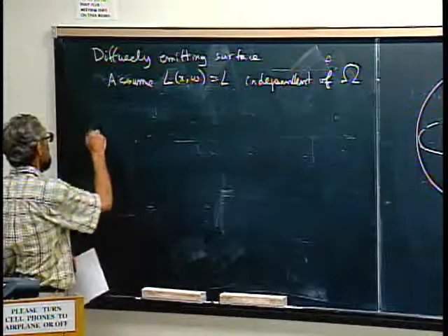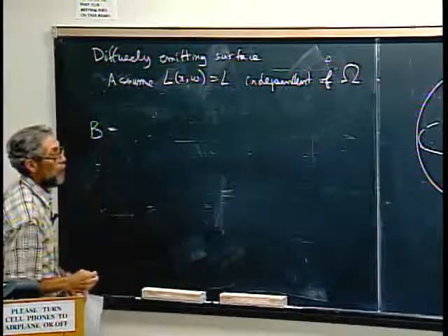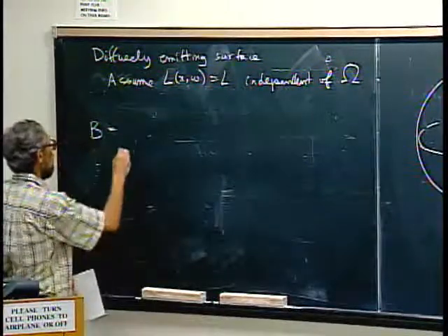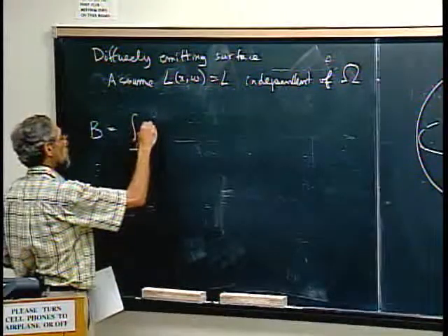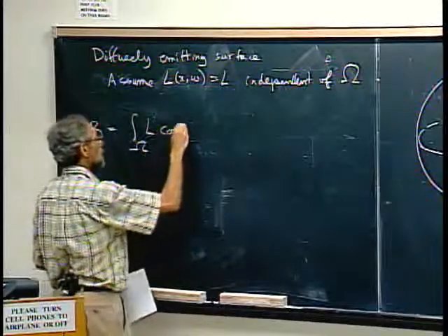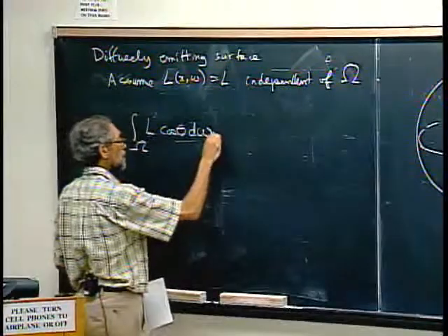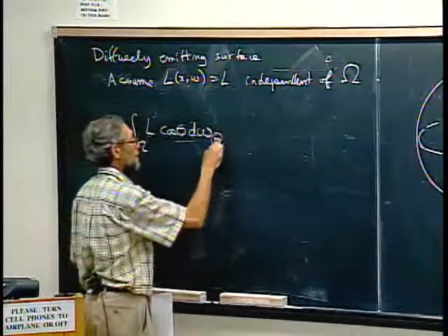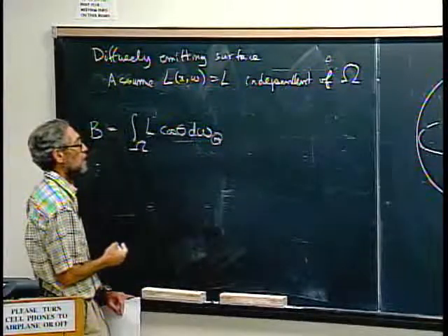And then if we want to compute the radiosity from the surface, just from that brightness, my integral is now the integral over the hemisphere of just constant L times cosine theta d omega, of the solid angle leaving on the unit hemisphere.